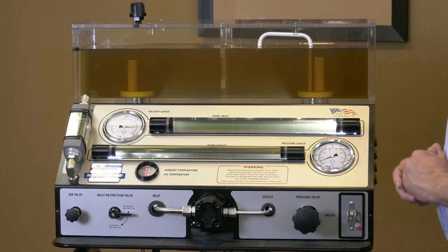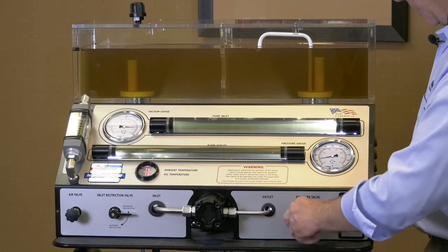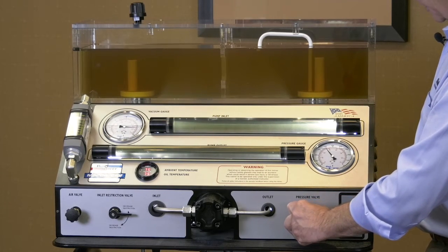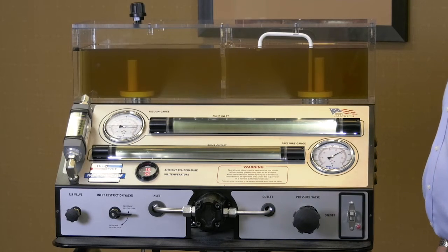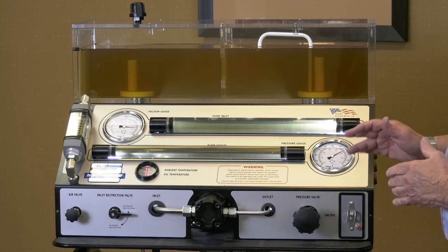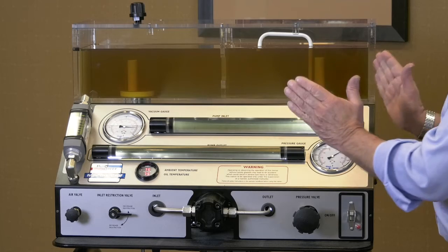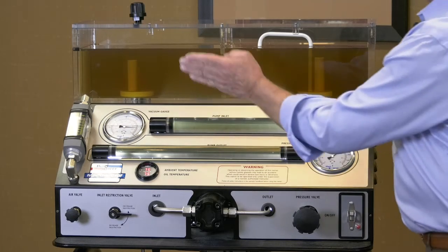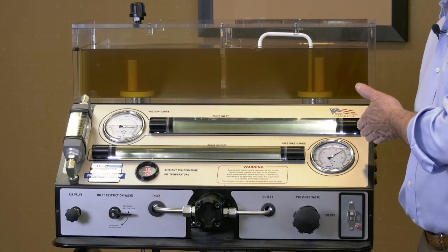Now I'm going to create some resistance. I'm going to close this valve slowly and push the resistance in the system up to 700 pounds per square inch. So the pump is pumping against a resistance right now of 700 psi. Once again, my operating parameters are 1.8 GPM, 700 psi.